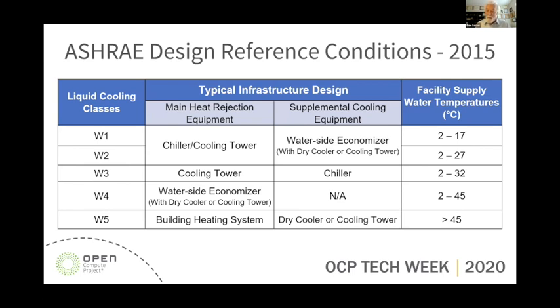So that drove us to inefficient cold temperatures because we had to go to the lowest common denominator. So we set up a group in the HPC working group to establish some temperature standards, and later those were adopted by ASHRAE, the W1 through W5.